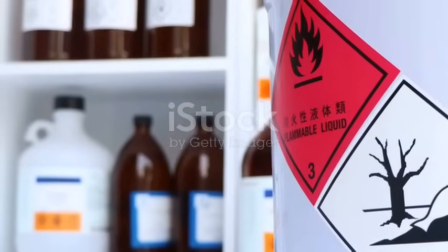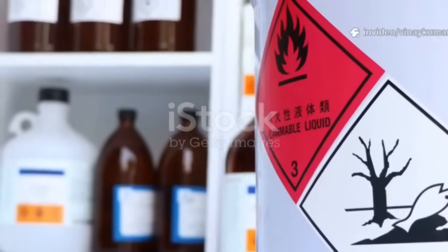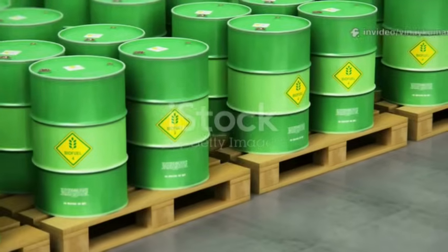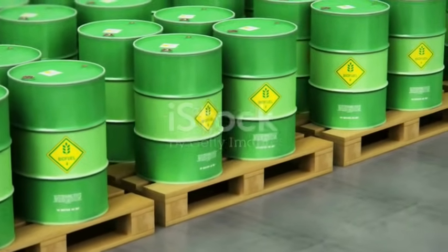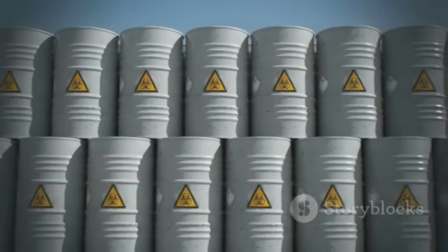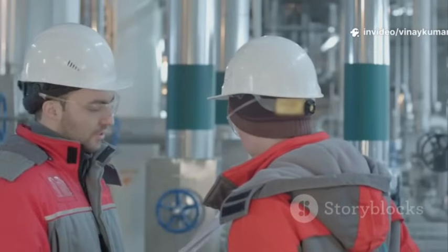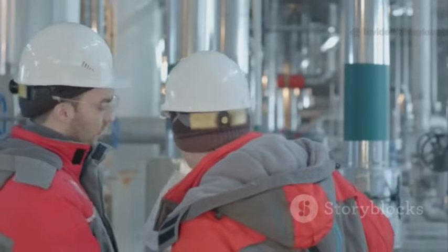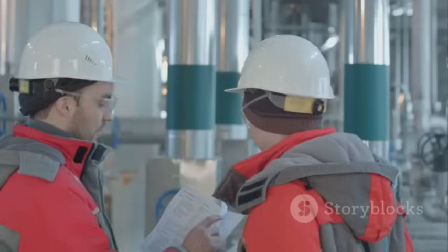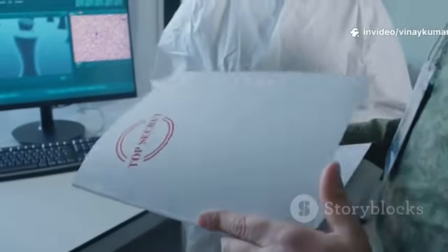First, the chemicals. You need to know everything about the hazardous substances involved, their toxicity, permissible exposure limits, physical data like boiling points and flash points, reactivity data, what happens when it touches, say, water or air, and what happens if it's not stored or handled correctly. This is the know your enemy part of the plan. This data isn't just for chemists in a lab. It's vital for operators, maintenance crews, and emergency responders who need to understand the specific dangers they might face at any given moment. It's the chemical's resume, and you need to read it carefully.